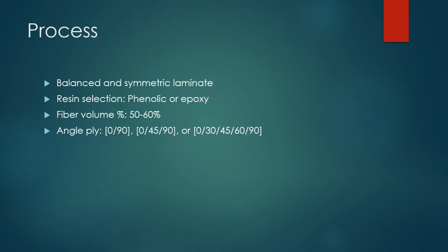Next, we ran fiber volume percent calculations using the micromechanics tool in the laminator to observe the effects of volume fraction on the mechanical properties of the laminate. And from there, we could figure out that the fiber volume fraction was not going to be a driving force for our design.